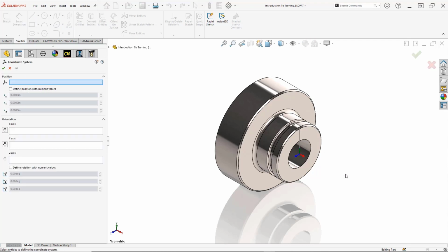From the cascading menu, select Coordinate System. Inside of the Property Manager, we are only concerned with 3 selections: the center point or SOLIDWORKS origin of our part, the gray vertical line which establishes the x-axis, and finally an entity, whether it is a planar face or a reference plane that establishes the normal to direction for the z-axis.